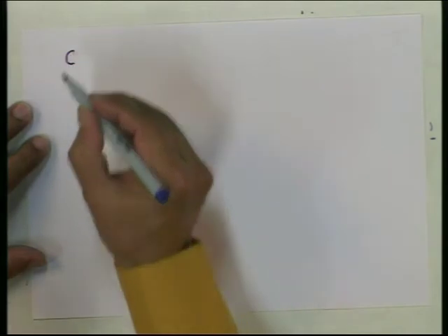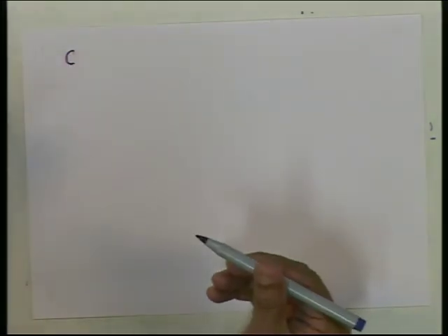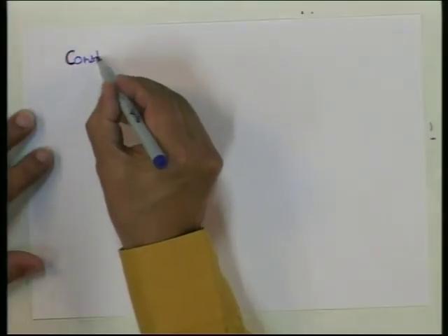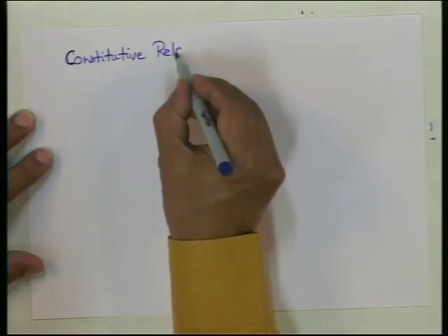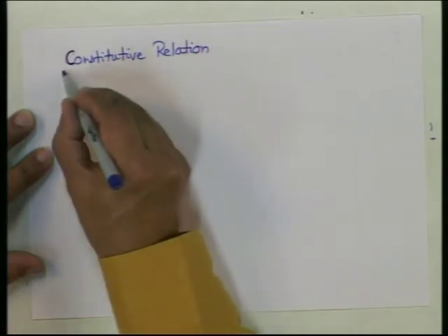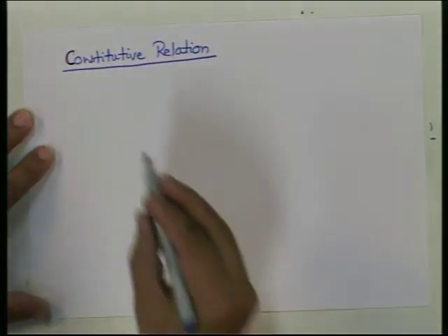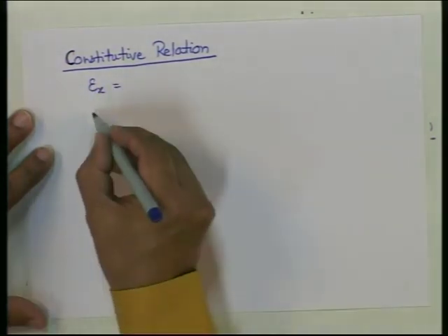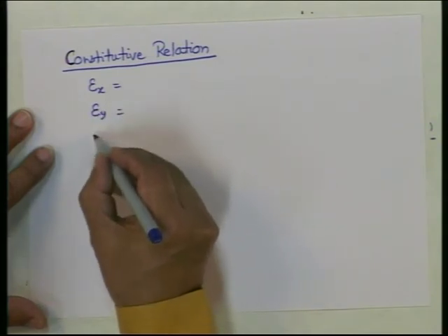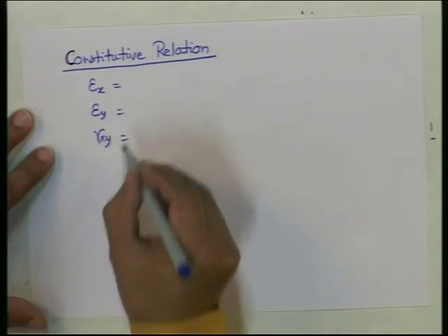Stress to strain or strain to stress, but as I told you, in finite element the relationship of stress in terms of strain is useful, but writing that relationship directly is not easy. So far we are not talking of the element type. Strain can be written in terms of stress easily, so we should always start like this.